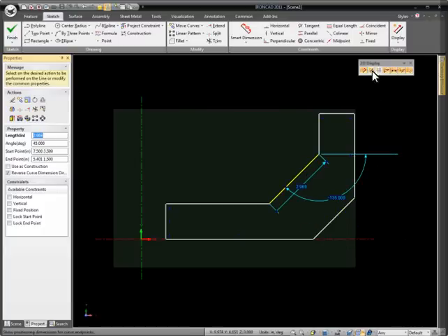Well, let's go back to our position dimensions real quick. You can see our position dimensions are by default, like I stated before, aligned to your XY coordinate system. However, you can redefine this information. For example, we want this line to move, and we want it to be a set distance from here. We can select either line to move, grab one of the indicators, doesn't matter which one, and notice when you grab it, you get a little handle icon, and you can snap to any other line. It's basically redefining what it's relating to.